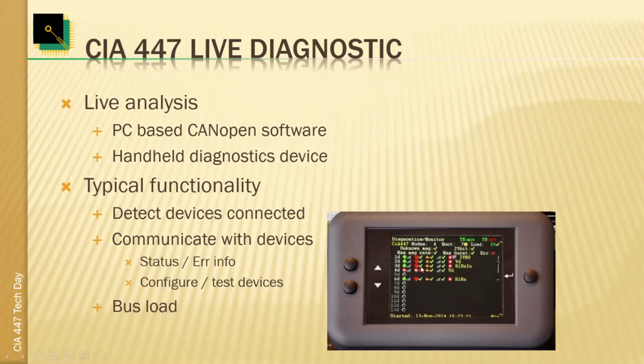So it's a little small here on the display, but literally it just gives you the node ID number. The green light says it's operational, and the bar graph gives you an indication about how much it communicates. A heartbeat is okay, response time is okay, and overall traffic load is okay. And here we see the shortcut for the virtual devices, IVN gateway. This should be roof bar light, roof bar sound, and things like that. So you have a quick overview of what's going on.